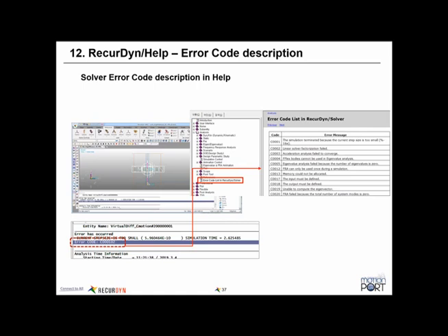Right. Yeah, and I certainly know the error message that I invoke most frequently. I'll be importing CAD geometry, doing some kind of work for somebody, and somehow a zero mass body will slip in there. Anytime you have zero mass properties, you'll get the error message with the singular matrix and so forth.